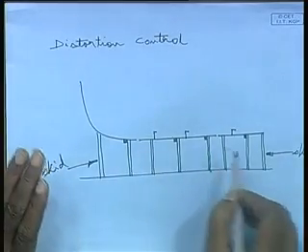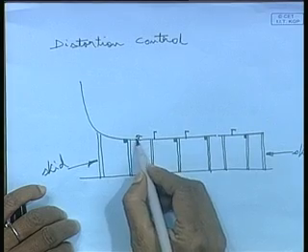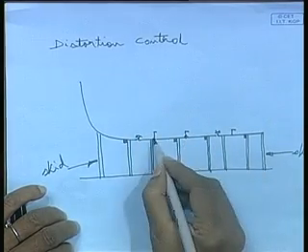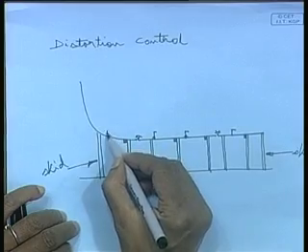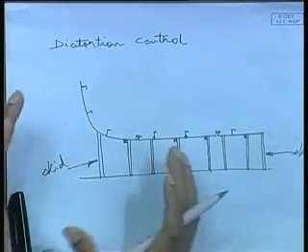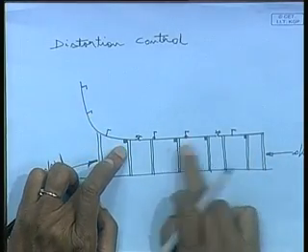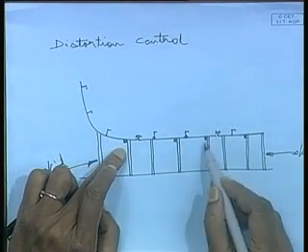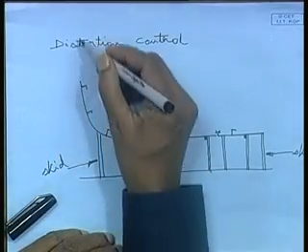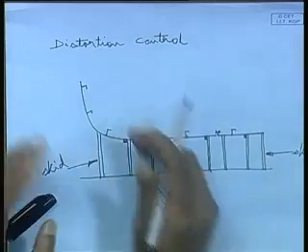So, once all these weldings were completed, also the welding of the stiffeners are completed, everything is done, then there might be a situation that you will have to release this from the skid. That means all these lugs which were welded are cut, and it is taken to some other fabrication station, wherein possibly you will add the side shells and other components, whatever it is.